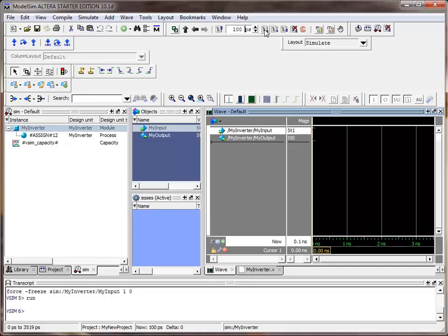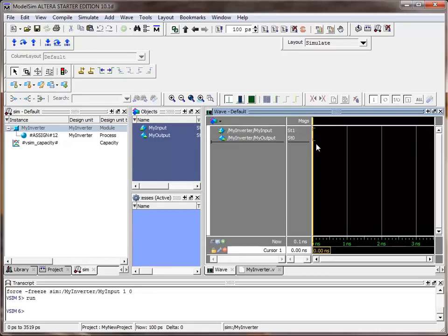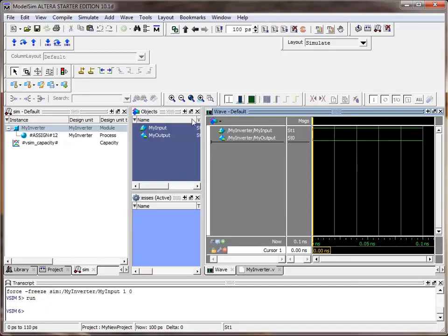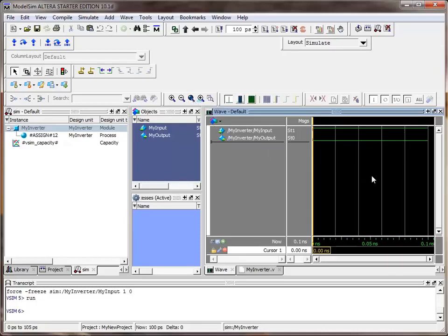So when I run that, now you can see that little 100 picoseconds as opposed to 1 nanosecond, 2 nanoseconds, 3 nanoseconds. So just because this window is set to show 3 or more nanoseconds worth of system time, I only simulated what's shown in this box, which is 100 picoseconds. So in order to see what's going on there, I'm going to zoom in with this zoom in button. I'm going to keep clicking that. And actually I want to fit it automatically to the size of this waveform viewer here, so I'll click this zoom full button, and you might have noticed it expanded to fit